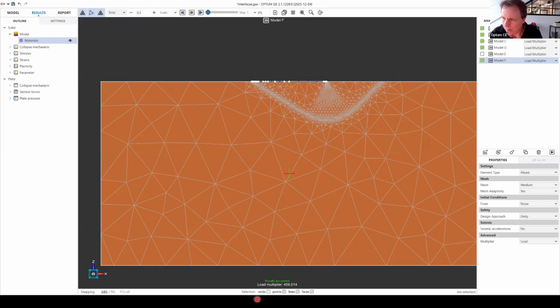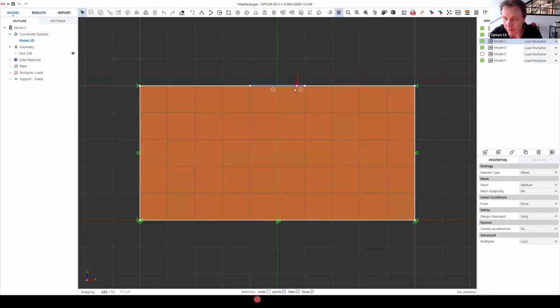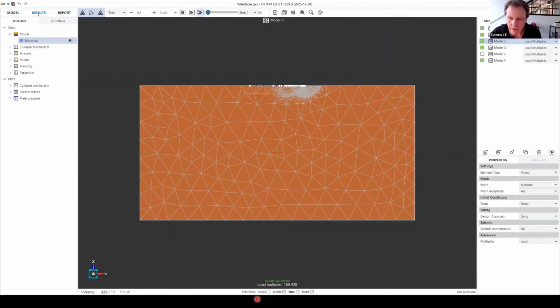And also you can start very easily if you have eccentricity, as in this case here. Have both a horizontal and a vertical load, and there's an eccentricity as well. So effectively a moment with reference to the center of the foundation. What you see is that things begin to lift off like that. They begin to lift off if you have the right interface conditions. And that brings me to that whole business with interfaces.